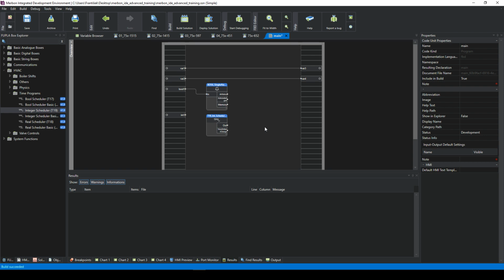So the main difference between BACnet and Modbus is that there are no registers in BACnet communication. This is only for Modbus. If you work with BACnet, there are objects which have their own properties, and the object is one variable. Okay, but it can be multiple variables. It's just the object type of communication. So we have to make sure you think about it in the right mindset.